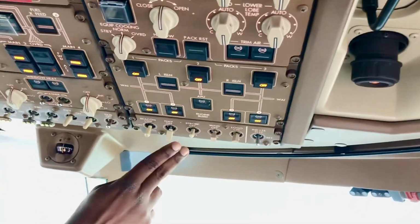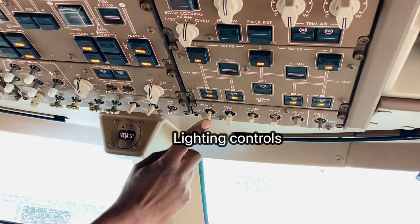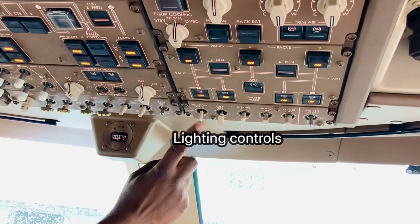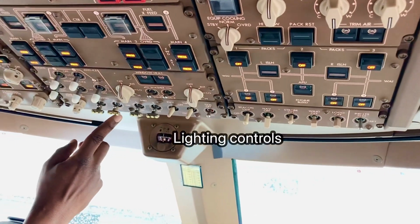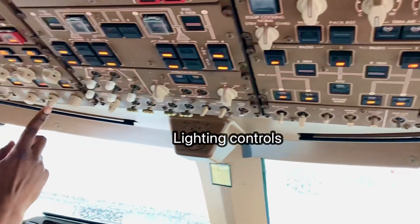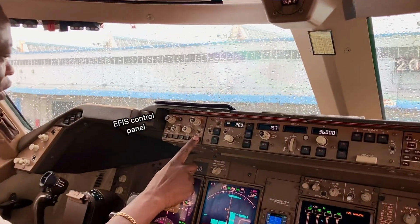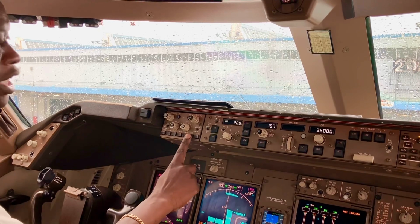All the lighting here, the strobe, the nav lights, the beacon. These are the red lights on the upper surface of the aircraft, and on the bottom one when we're about to start. Taxi lights, runway turnoff, all here, the lights are in the right position. Come down here, I do a check on this, make sure the QNH is correct, and there's data and position that I may select here.